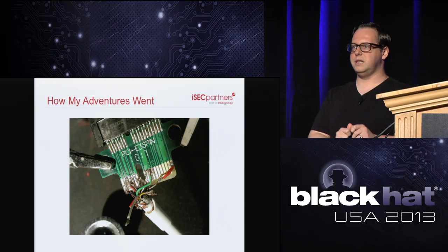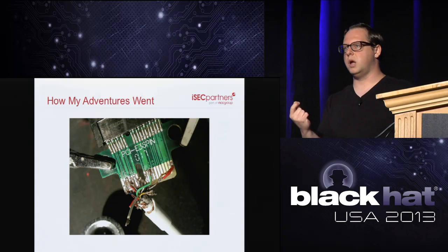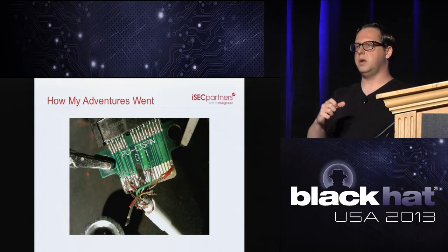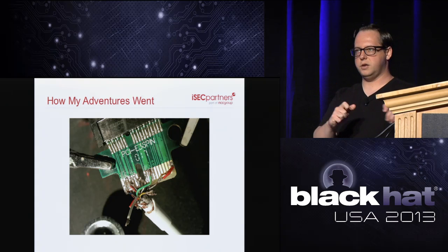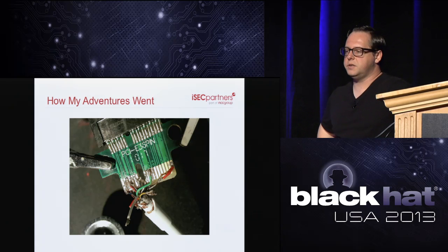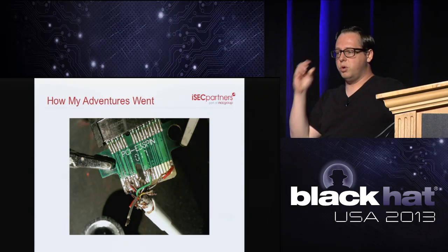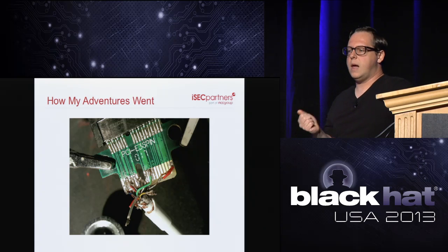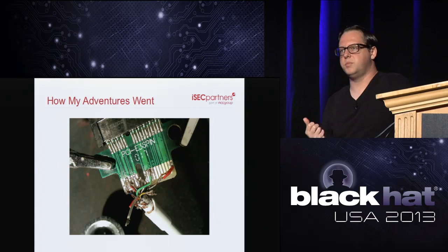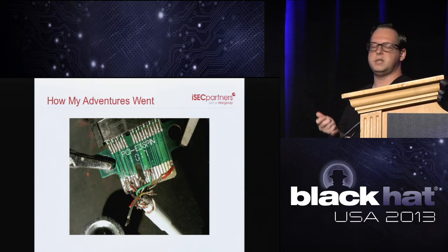It was really difficult to actually strip these wires, and then getting down to the even smaller wire, I just had to use a really sharp clipping tool and be very careful not to cut those thin wires. And then soldering this on, there's not a lot of room. We could pull these out. We can use some other wires. I wanted to try to make it as compact as possible, and then the end result would just be epoxied so that it would be protected.